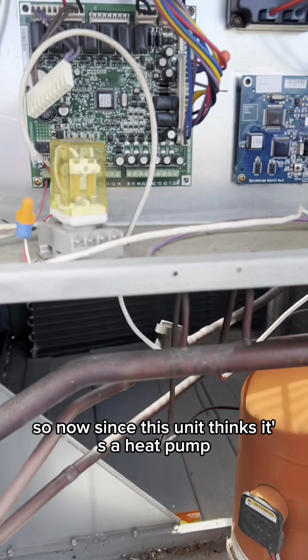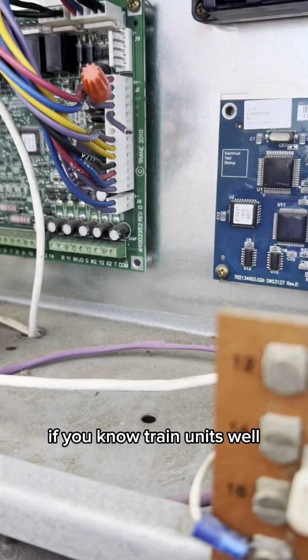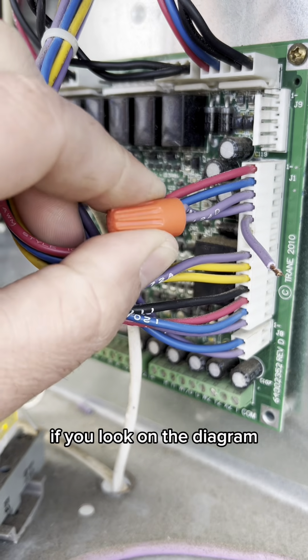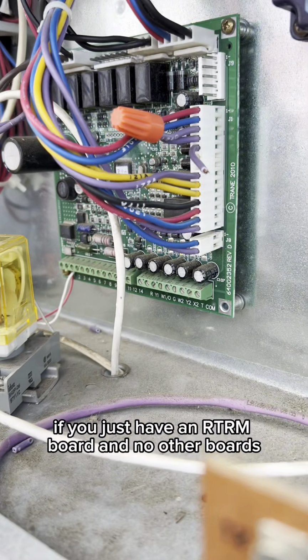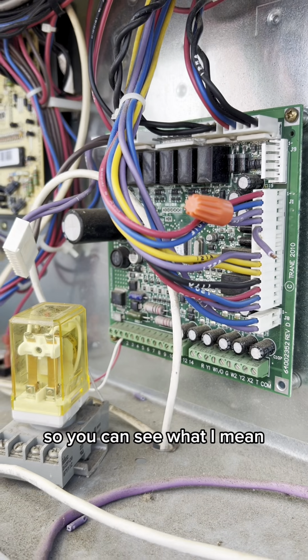So now, since this unit thinks it's a heat pump and it's having some sensor failure, troubleshooting it, we came up with a few things. Now, the first thing, if you know Trane units well, you know this purple plug right here, this purple splice. This here, if you look on the diagram, will dictate if it's a heat pump or not. If you just have an RTRM board and no other boards, this here will tell the unit in its configuration that it is a heat pump. I'll show you on the diagram here so you can see what I mean.